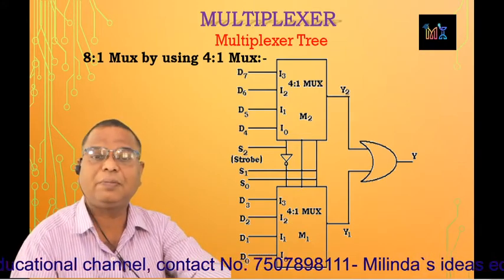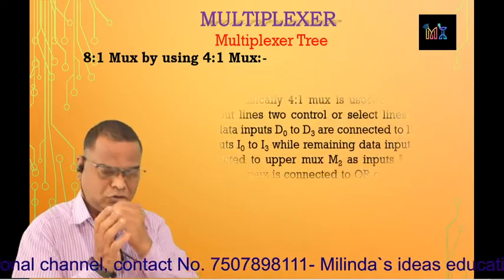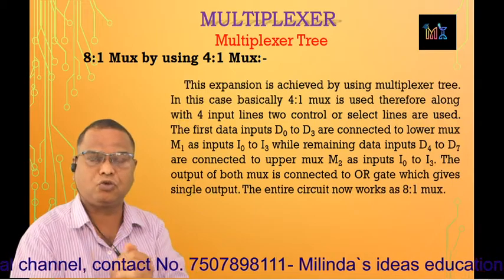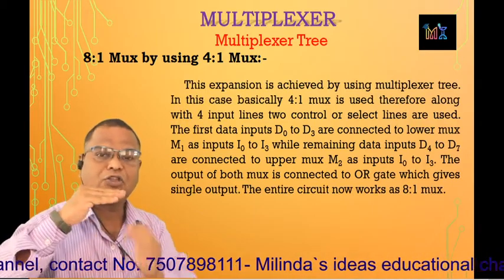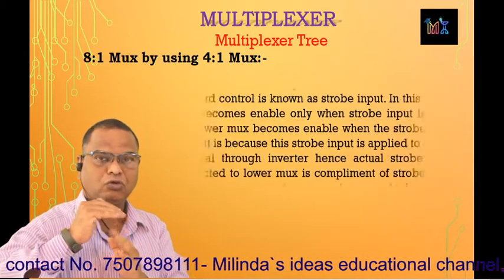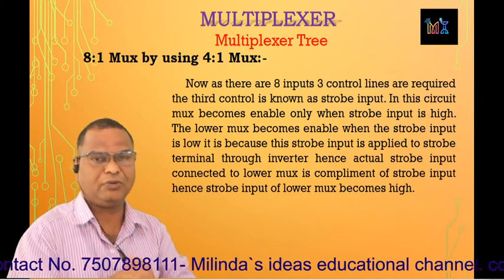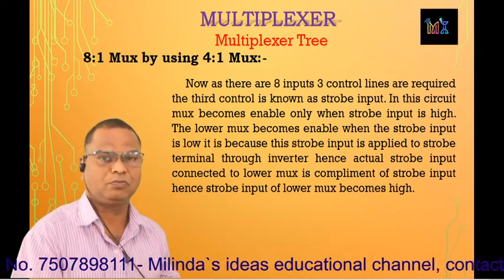Now how does this multiplexer work? The control inputs S0, S1 and S2 are common to both muxes. When the strobe input is low, the mux is in disable mode, and when the strobe input becomes high, the mux is in enable mode.